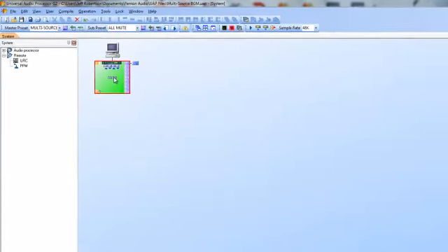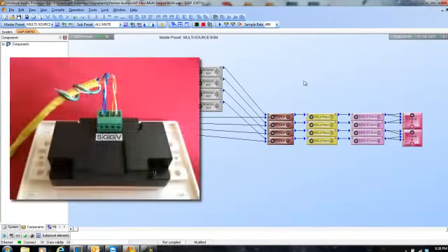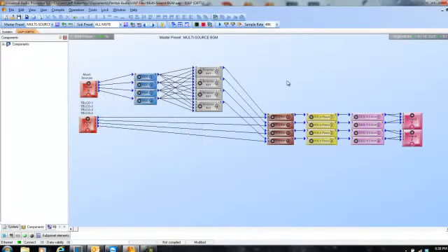A quick refresher: I've got a demo design up here right now, and I've just got one of my little RAC5s, which is a 5-position selector switch with a volume control on a single Decora style plate. It's wired with standard Cat5 4-pair back to the UAP, and it takes up analog control inputs number 1 and 2. Input number 1 is where I wired the selector switch, and input number 2 is where I wired the volume control portion of the switch. Let's say I have this 4x1 selector switch in room 1, and I want to control the output level going to room 1 through this output right here.